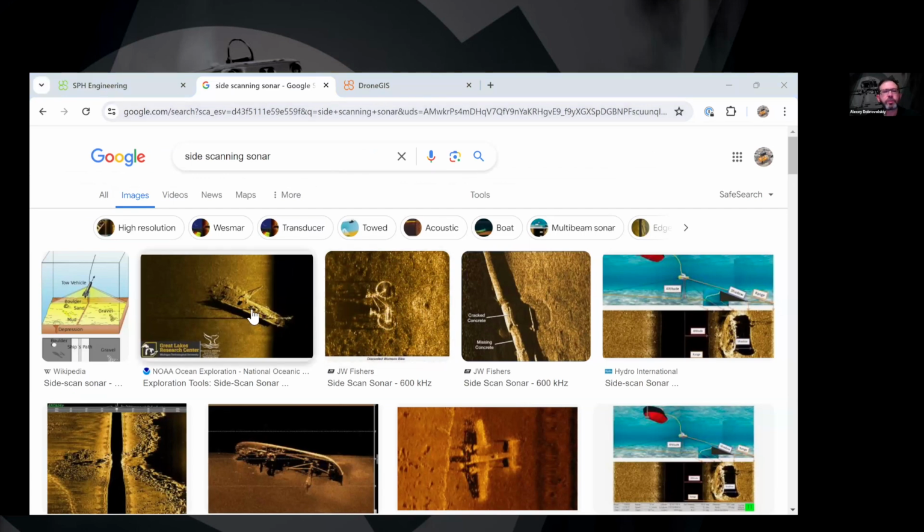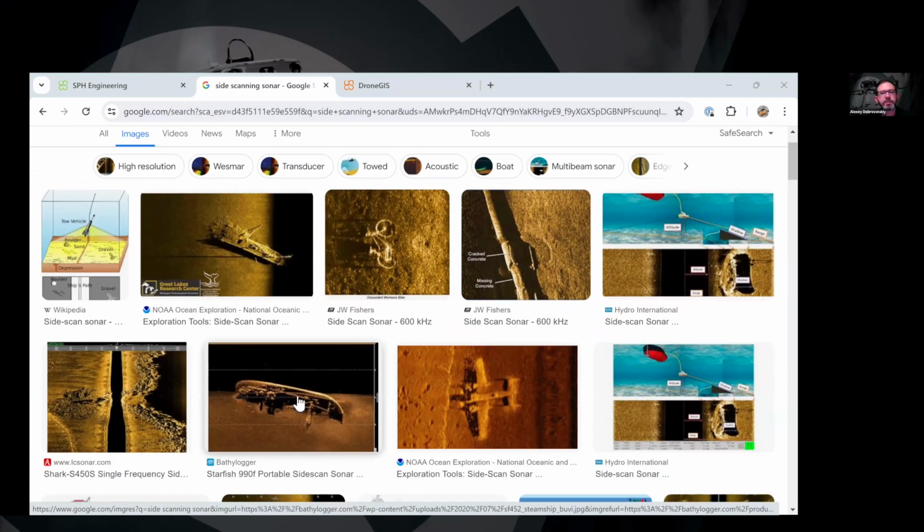It is what you can get from side scanning sonars. They generate synthetic pictures of everything on the bottom. Very exciting result, but they are mostly search and inspection tools. Using side scanning sonars, you cannot measure depth with high precision, which is usually necessary for bathymetric surveys.